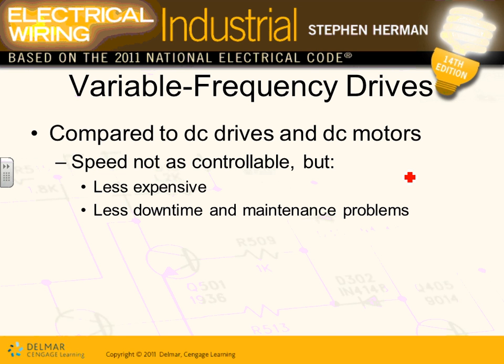Now, what happens if you have an AC motor, gentlemen? You need to control the speed of an AC motor, an induction motor. You ask for an AC drive. Did you hear the word AC drive? If you have a machine, you guys, VFDs. That's your VFDs. VFDs control the speed of an AC motor. DC drives control the speed of a DC motor. Does that make sense? So if you want to control the speed of an AC motor, guys, VFD is your baby.